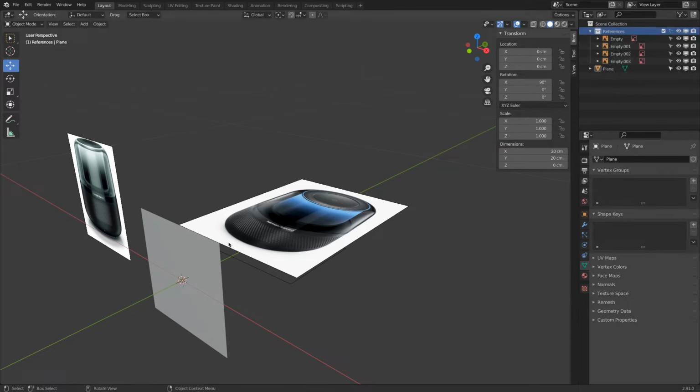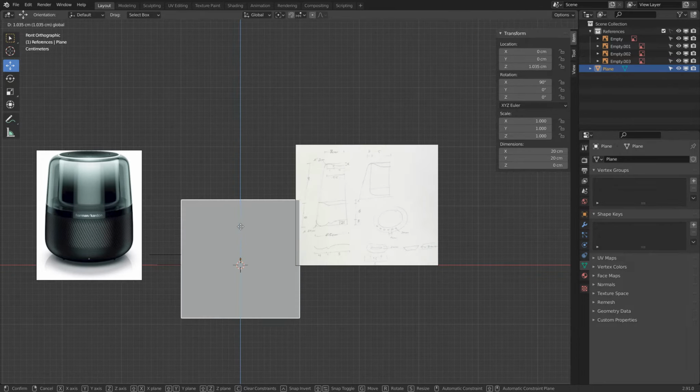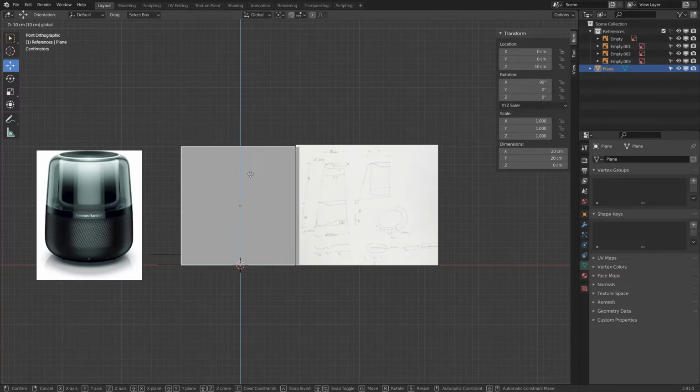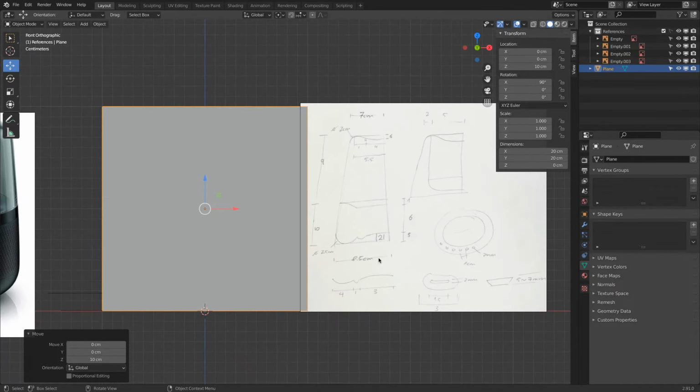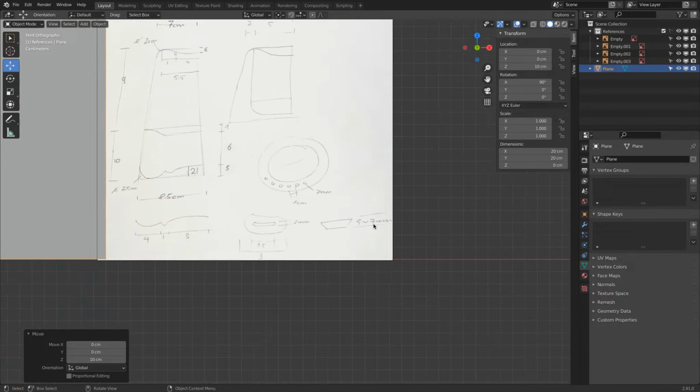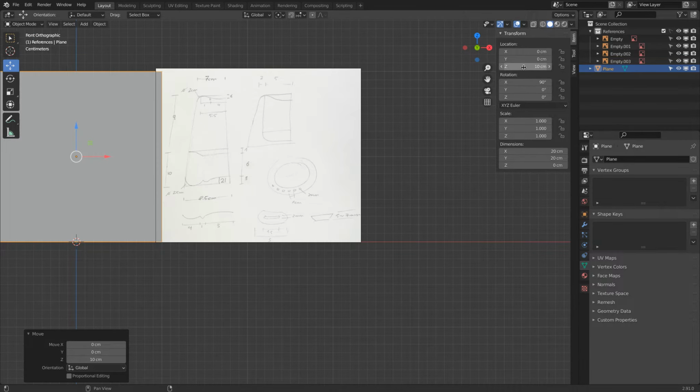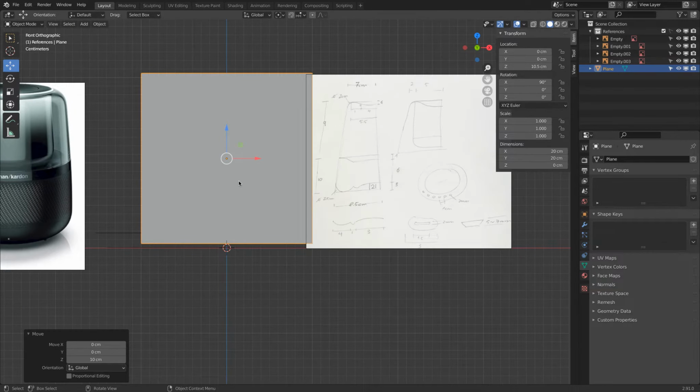So we have grid snapping still turned on, so we move this one up, hold the control key and snap it to the ground. Very good. The whole object is 5 millimeters off the ground. So we can go to Z and then here type in 10.5. That moves the whole object a little bit more up. Nice.